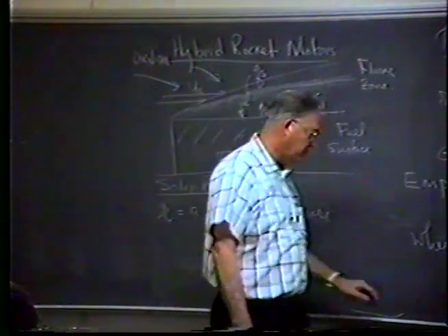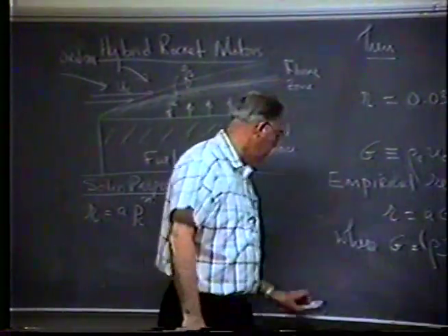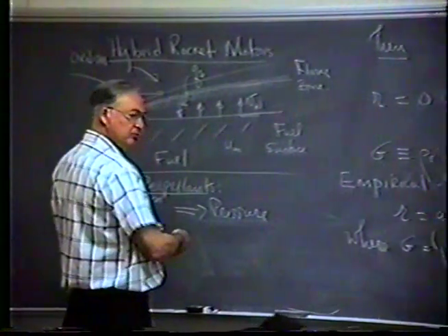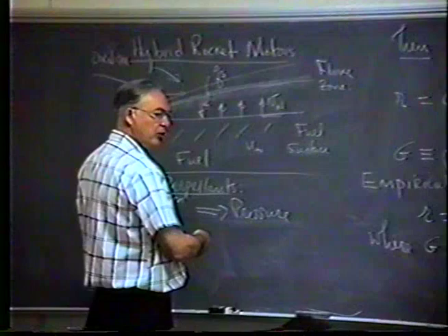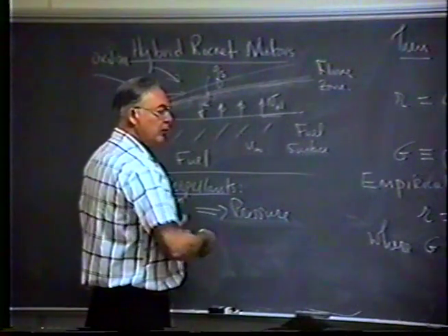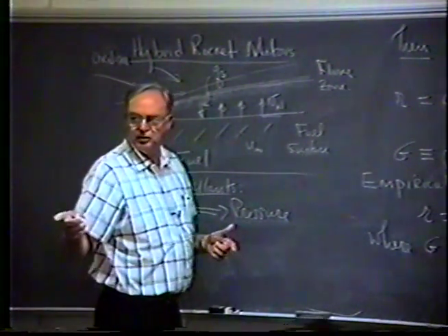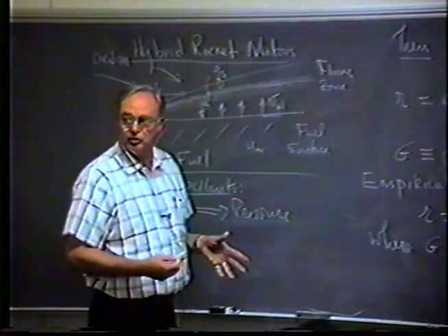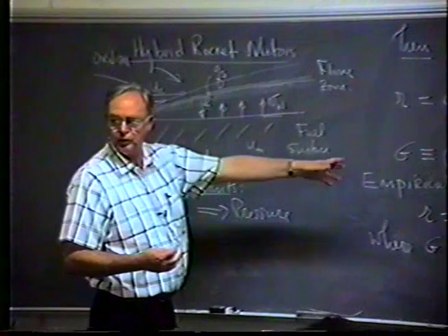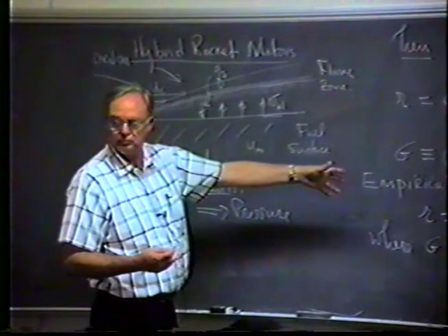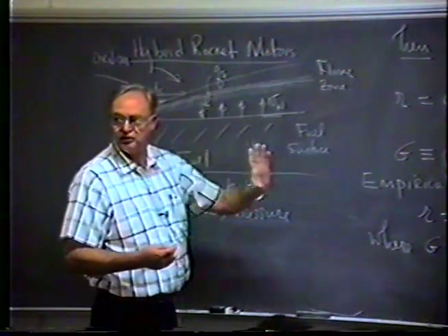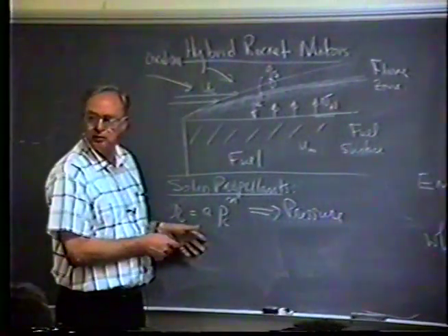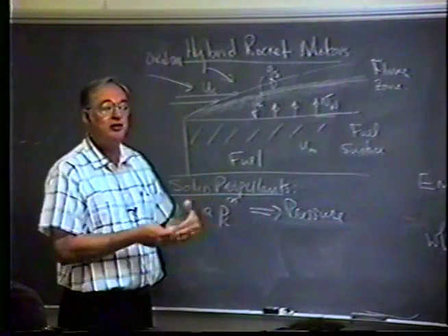Ben was saying though that the burn rates are so much different. Well, now you've got a mixture of that one and this one. That gets quite a bit more complex. Glenn? So what is the fundamental mechanism driving hybrid rocket motor surface regression rate? The mass flux into the center port. What's the fundamental mechanism in this solid rocket? Chamber pressure. Quite different mechanisms.